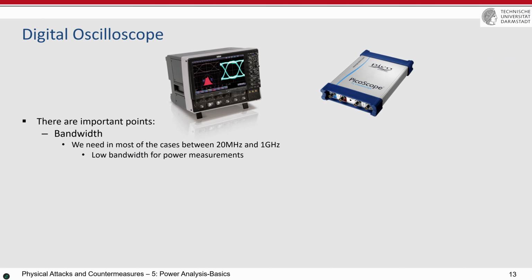Even in power consumption measurements, because you have some noise, you can actually turn on the internal low pass filter of the oscilloscope. For example, these oscilloscopes have some low pass filter, not a digital one, an analog one, that you can turn on to 20 megahertz. And it doesn't matter if your oscilloscope supports up to 1 gigahertz or not. 20 megahertz is enough for power measurements, usually.